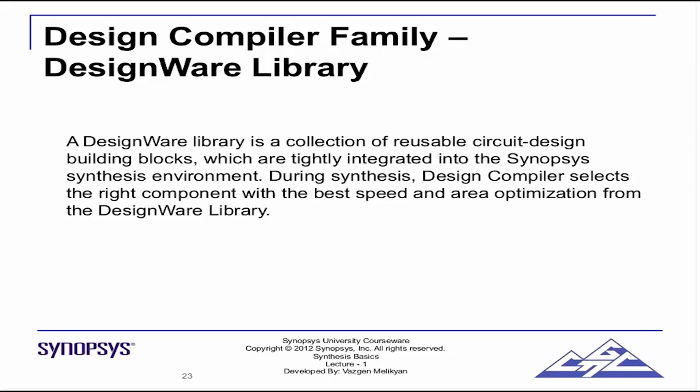During synthesis, Design Compiler will select the right component with the best speed and area optimization from the DesignWare library. Many times you do not need to specify this in your RTL code, but I have seen people who are very particular. For example, they want that in all cases the multiplier I use should be a Booth multiplier.